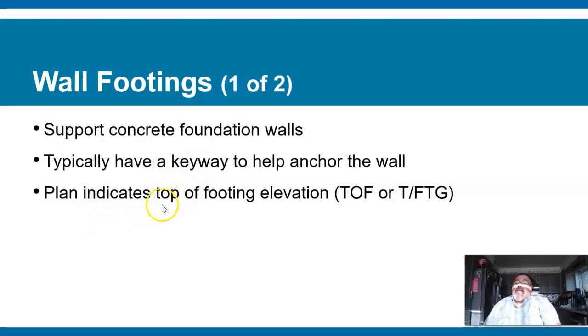A plan indicates the top of the footing, TOF, or T/FTG, right? Top of footing, TOF, or T/FTG. That's what the plan indicates. So that's what you see when you're looking at a plan. You see the tops of the footing elevation.